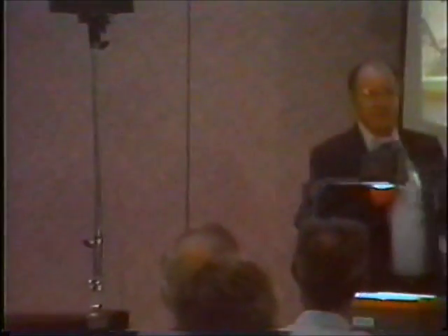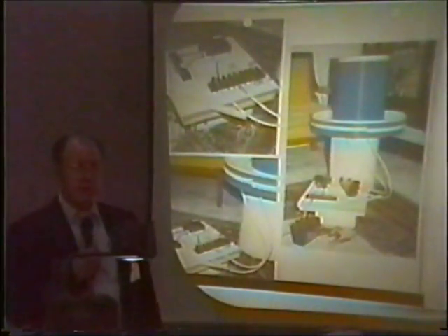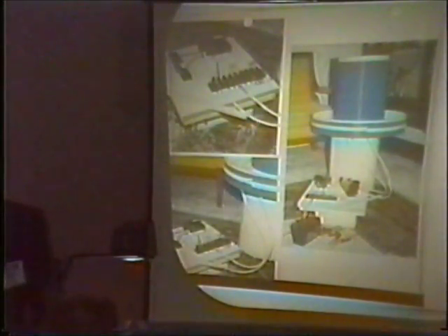It has 3 turns. Your L1 coil's got 3 turns? Yeah, this one has 3 turns of number 8 wire. And the L2 coil has how many turns? The L2 coil has 130 turns on it, and it's number 14, I believe. It's multi-strand wire, because if you use the solid wire, it's very difficult to control and make it look nice. The solid wire goes its own way.